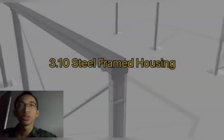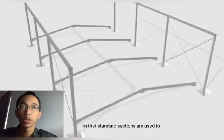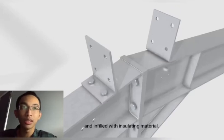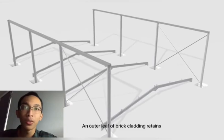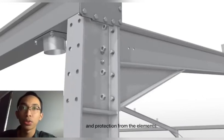Steel framed housing. Steel framed housing is similar to timber frame in that standard sections are used to make up a structural frame. The frame is lined with plasterboard and filled with insulating material. An outer leaf of brick cladding retains a traditional image and provides protection from the elements.